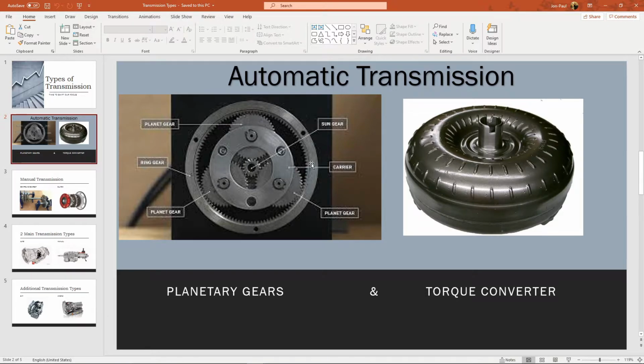And what makes an automatic is that it has a torque converter, not the fact that it changes gears by itself, because dual clutch transmissions change gears by themselves. CVTs, you throw it in drive and it goes. And there are some manual transmissions that are shifted electronically by the computer. And they're not great, but there are some. So that's what makes an automatic an automatic.